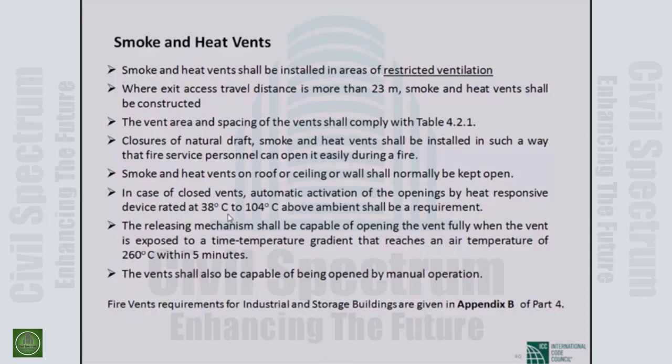If the building is not properly designed, the smoke will go to the stair. So you have to restrict this smoke propagation, and not only restrict propagation, you have to allow the smoke to go out. So you need some vent so that smoke can go out.